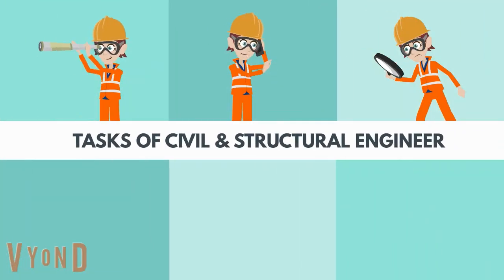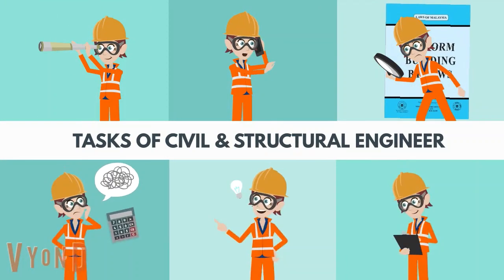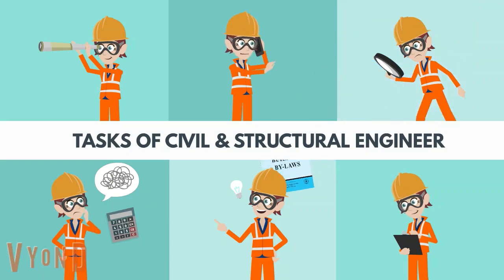In this scenario, civil and structural engineers have to produce civil and structural plans for the client to acknowledge their bungalow design and for approval. We need to confirm the design requirements of the architect in our drawings to avoid mistakes. Furthermore, we have to submit procedures for planning approval such as the building plan and relevant Form G and Form F for the Certificate of Completion and Compliance, known as CCC, before the start of construction.